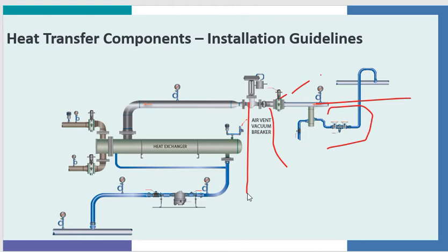In the vertical, you can have condensate buildup in the valve during shutdown, and when you open up the valve, condensate will come through and flash and tear the trim outside of the valve. After the steam control valve, expand the pipe at least 1 pipe diameter.